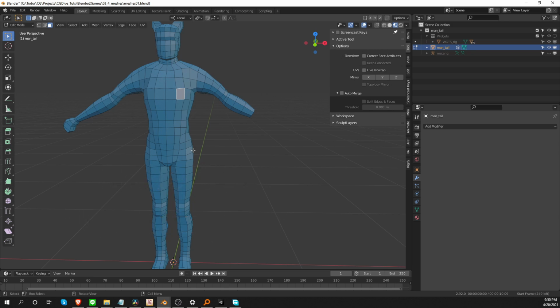But anyway. Now this type of messy geometry can create different types of problems. I don't think I can list them all, but one problem that I see a lot, and that is because of my series on Rigify, many people, when they try to parent a mesh to an armature, get bone heat weighting error. This error does not have one single solution, but very often it is because of messy geometry. The automatic weights in Blender are great, but they need relatively clean geometry to work correctly.